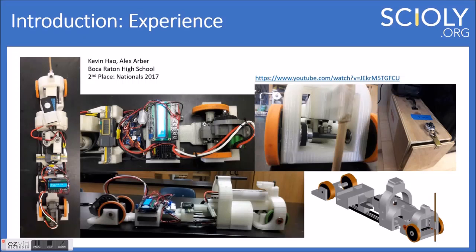You can see the same voltage regulator in here for our electronics. That didn't change from the previous vehicle. And the encoder, it was the same encoder, but now if you look at this profile picture over here, you can see how we use this belt. We use this belt system to remove the encoder from the front axle and offset it towards the rear. If we had the encoder along the same axle, directly connected to that front axle, our vehicle width would be larger.